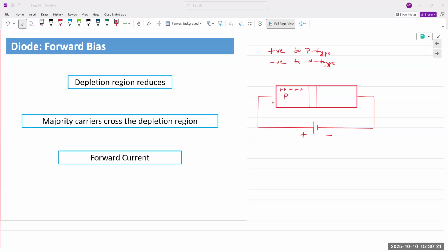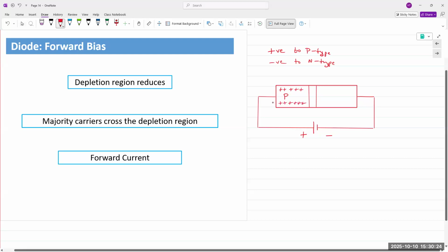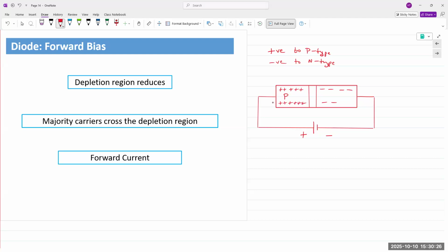All right, so we have positively charged holes and negatively charged electrons on either side of this junction. What happens when you have positive voltage going there? Holes are pushed towards the junction. Electrons are again pushed towards the junction from the other side. So the depletion region starts to shrink. The charge carriers are absorbing more energy. Because they have energy, they're able to flow across the junction. Depletion region shrinks, and because it shrinks, now current can start flowing once that barrier is overcome.